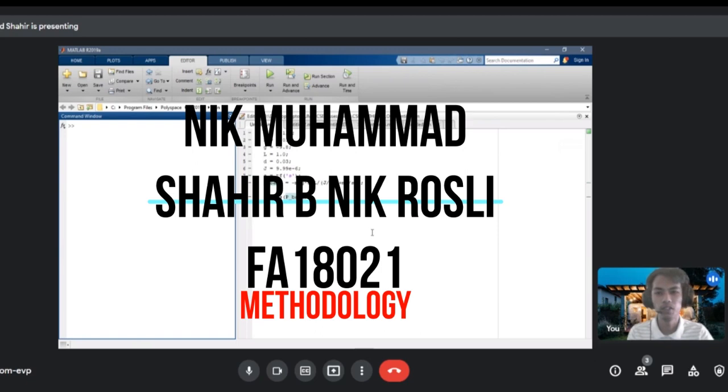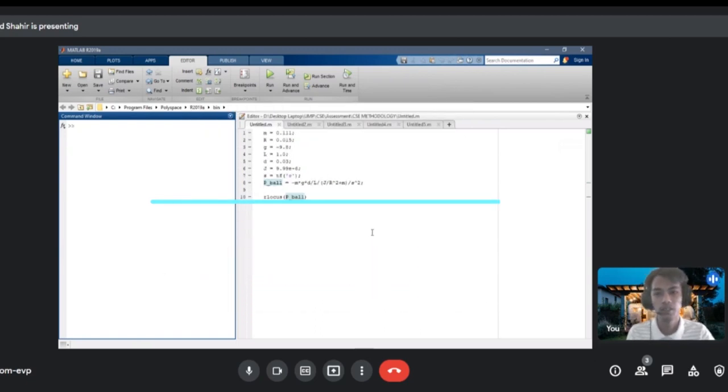I will start with the open loop root locus. The main idea of root locus design is to estimate the closed loop response from the open loop root locus plot by adding zeros and poles to the original system. The root locus, and thus the closed loop response, will be modified.